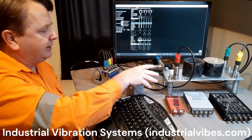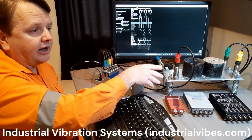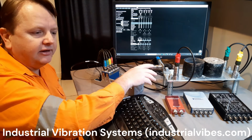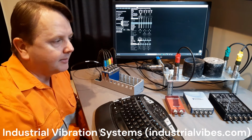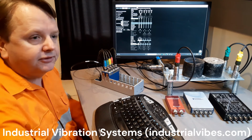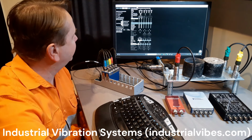So I'm expecting, because this is effectively a rigid body mounted on soft springs, I'm expecting 6 clear natural frequencies at fairly low frequency. So we've got the x-axis scaling on the spectra going up to 20 Hertz.